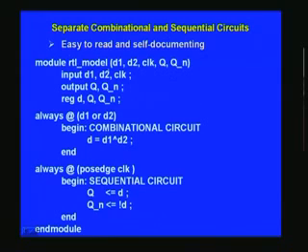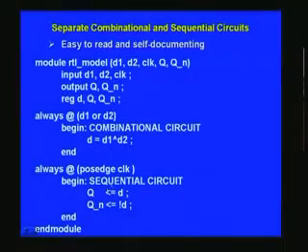Like this you may have several such modules, but it is illegal to nest modules within modules. Nesting is putting a module within a module. For example, I cannot say somewhere here, before the endmodule, call another module, say sequential module. I can't put another module. That is an illegal thing in Verilog coding. Once you identify the actual module name, you then list the IOs here, and you can put them in any form that you want. IOs can be in any order that you like, and these are all separated by commas.